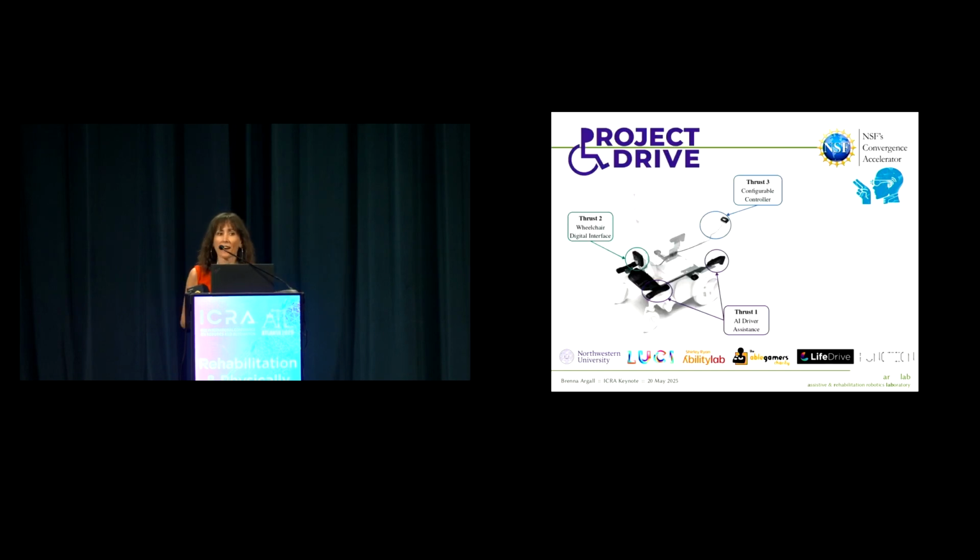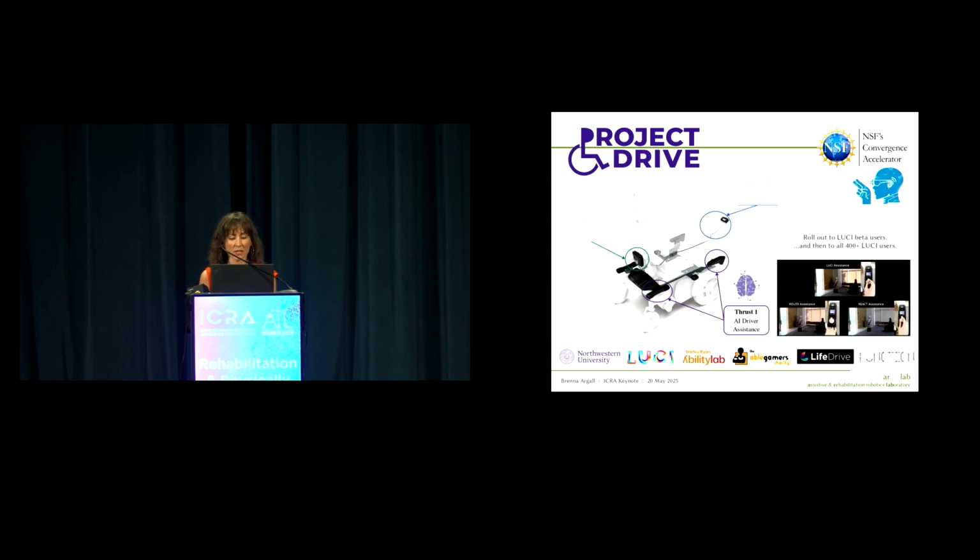On this project, we have 3 main technical thrusts that we are pursuing, and I'm going to zoom in just on one of them for the moment, and this is the robotics intelligence that we are adding to the wheelchair driving. Lucy is already a commercial product. It's a sensor, a retrofit to existing powered wheelchairs that adds on sensing and compute, and it'll detect obstacles in the environment and drop-offs, and it will slow or stop the wheelchair in response to those dangers. What we are doing is expanding the capabilities of Lucy's assistance to do things like actively drive around obstacles. And we are on track to push out the first of this work within the Lucy product by the end of this calendar year.